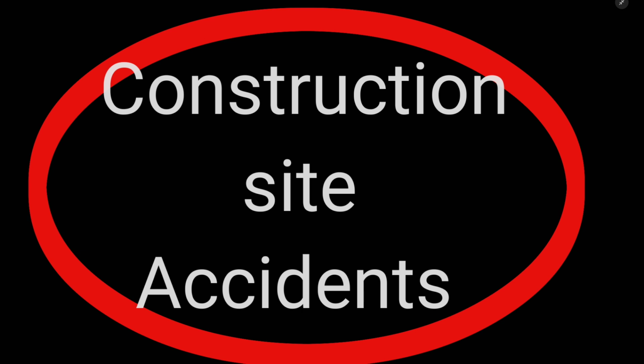Seventh is forklift accident. Forklifts are essential on construction site but can be deadly if not used correctly. Ensure forklift drivers are properly trained and always follow speed limits. Additionally, pedestrians should avoid walking near forklifts and warning signs should be placed to indicate forklift activity.